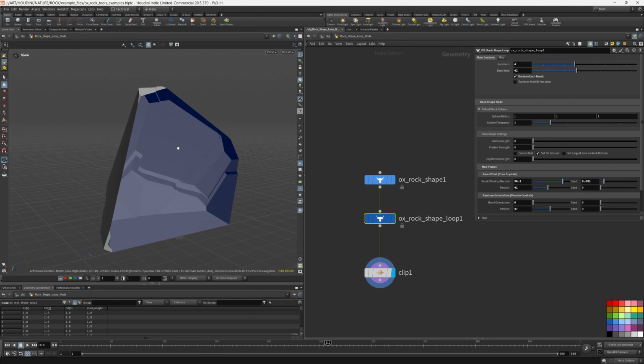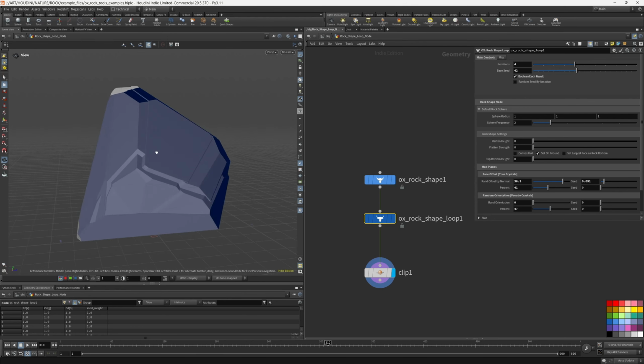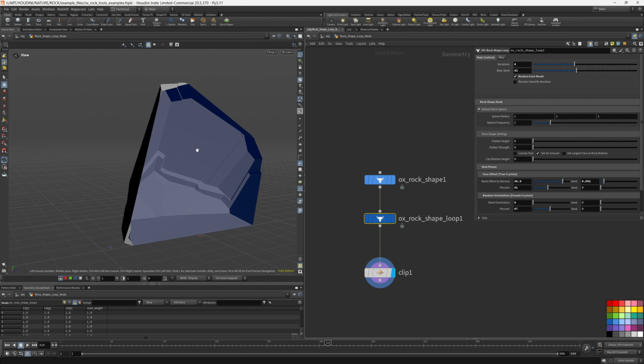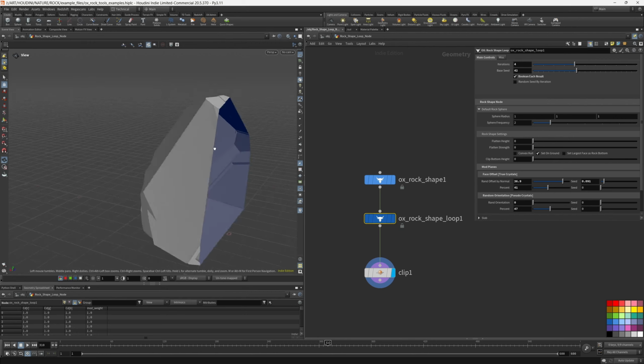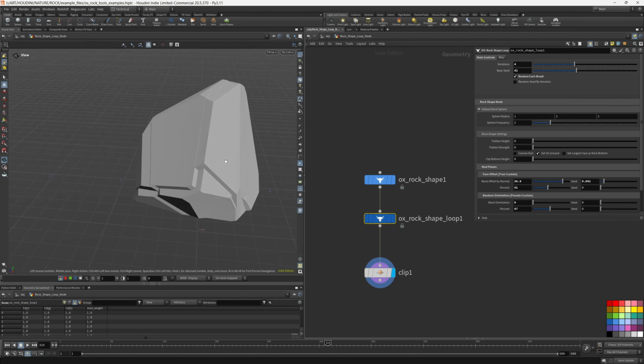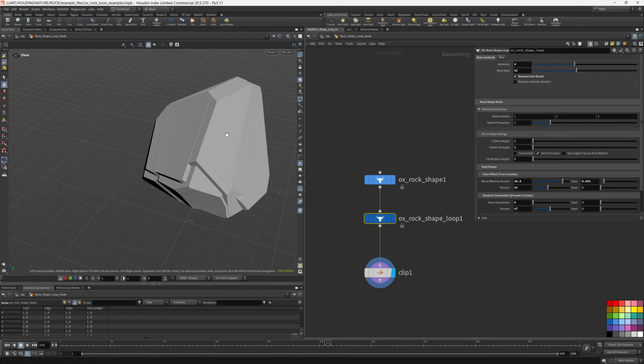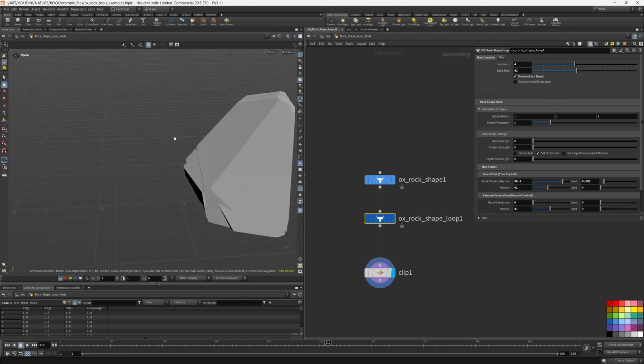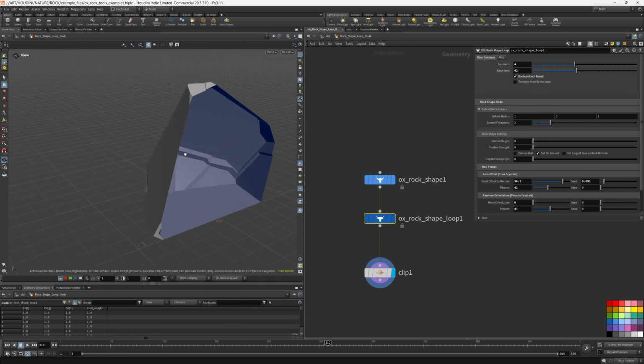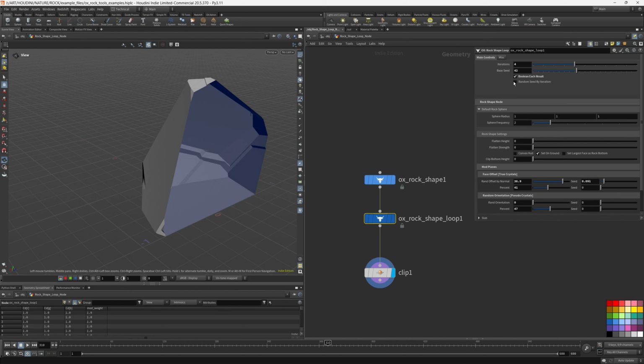Now, in Houdini, when you're going to use a Boolean on multiple geometries, if there are shared faces, I notice that the Boolean node suffers a lot. If there's a plane and another plane intersects that plane, and a Boolean operation runs on them, it'll really bog down Houdini and create some glitchy results. So what I have implemented in here is a protective offset.